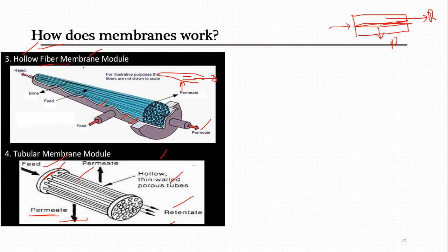They are leaving from this end. Maybe you will be thinking how the mixture feed can get mixed with permeate. No, you will have a tube sheet here which will stop the mixing of your feed with the permeate. The other components, which can't penetrate through this membrane, will just leave towards the opposite end and are rejected. As I have shown you with one tube, some can penetrate through this membrane, can permeate through this membrane.